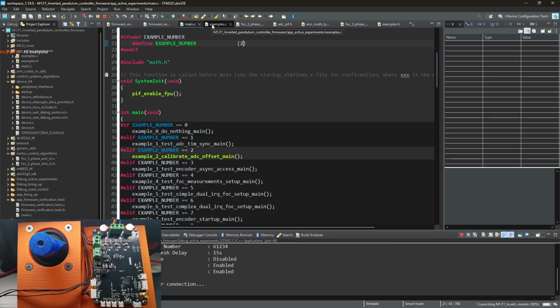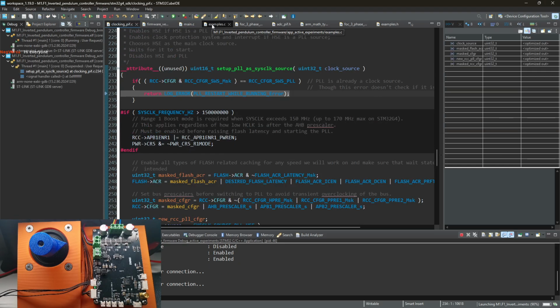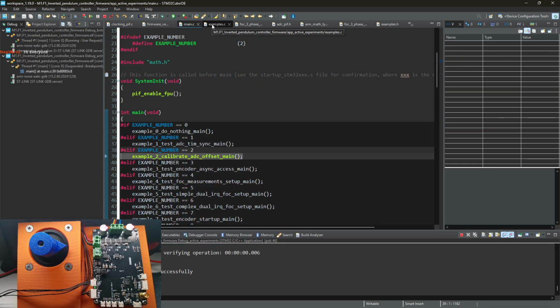Well, Warsaw. Actually, Warsaw, I did check the thing we were discussing yesterday about microcontrollers, about the versions with 3 and 5 ADCs. And the interesting thing is that I cannot put any of the ones we found directly into the board for it to work as we discussed, so that we can offload the ADCs to other ADCs, not 1 and 2, but 3, 4, and 5.